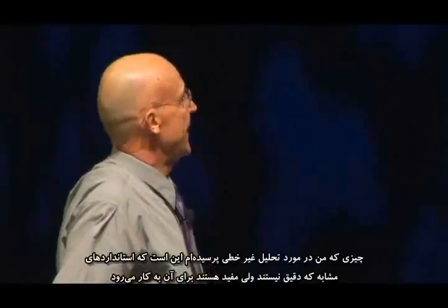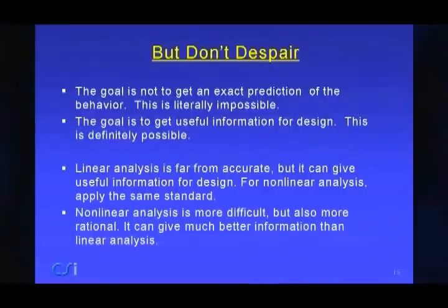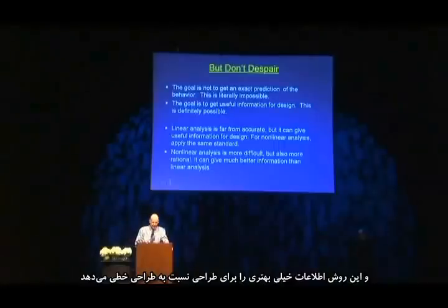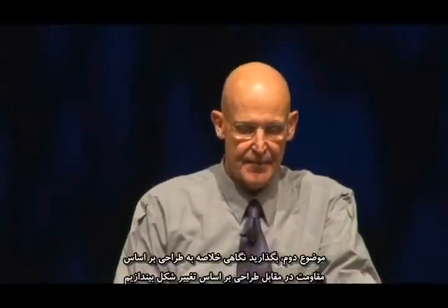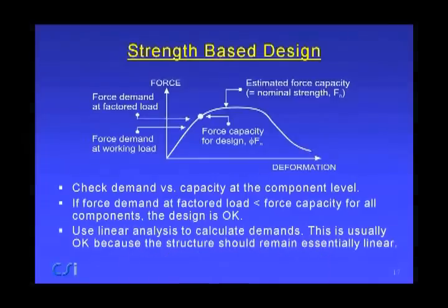And what I would ask for nonlinear analysis is apply the same standard. Not is it exact, but is it useful? And I would argue that nonlinear analysis, although it's more difficult, is also more rational, and it can give much better information for design than linear analysis. So the second topic is, let's look briefly at strength-based versus deformation-based design.